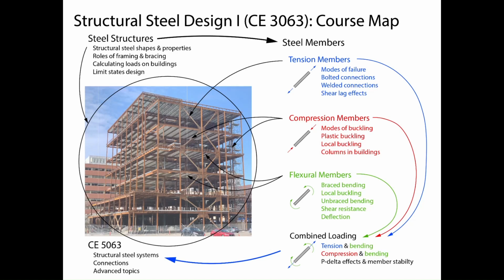And so you're going to design some tension members for the maximum factored tension force. You have to calculate the maximum factored tension force on assignment 3. You would take the tension from wind, earthquake, dead, live, and snow loads from the notional load effects, factor them up, and design a brace to take that factored tension force.